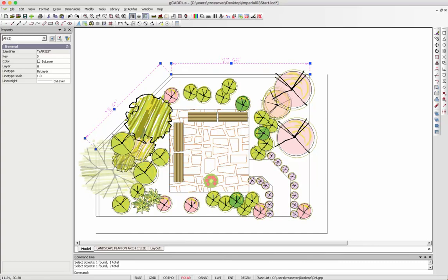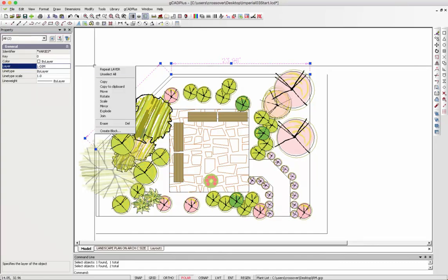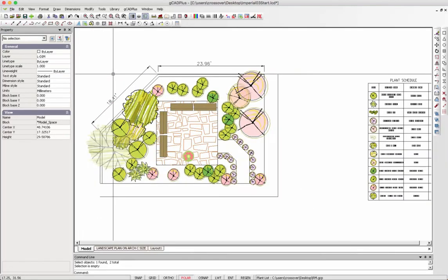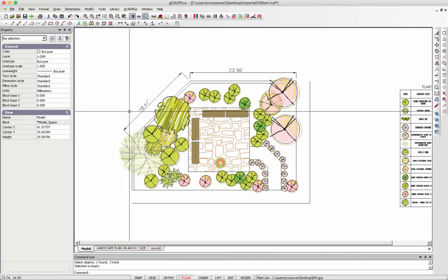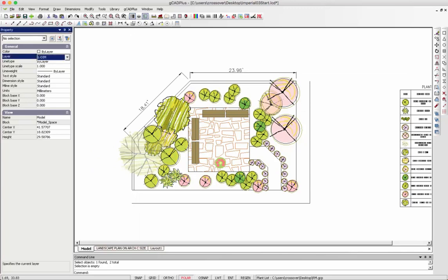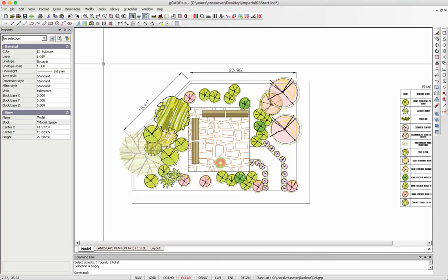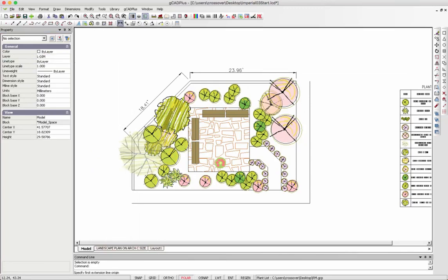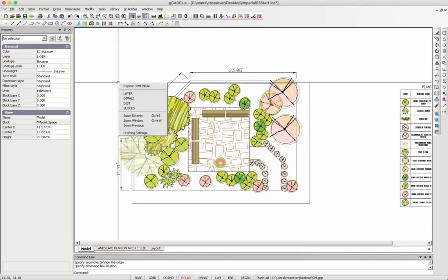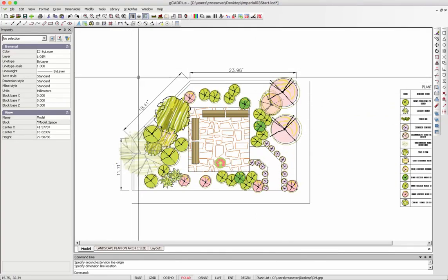I can do that by coming over to the properties box and move to layer LDIM. If I was going to do an extensive amount of dimensioning, I would make the active layer LDIM as we have here, and let's pick another dimension for the outer part of the wall down to here, and then position the dimension like so. Repeat it, so I just hit the enter key.